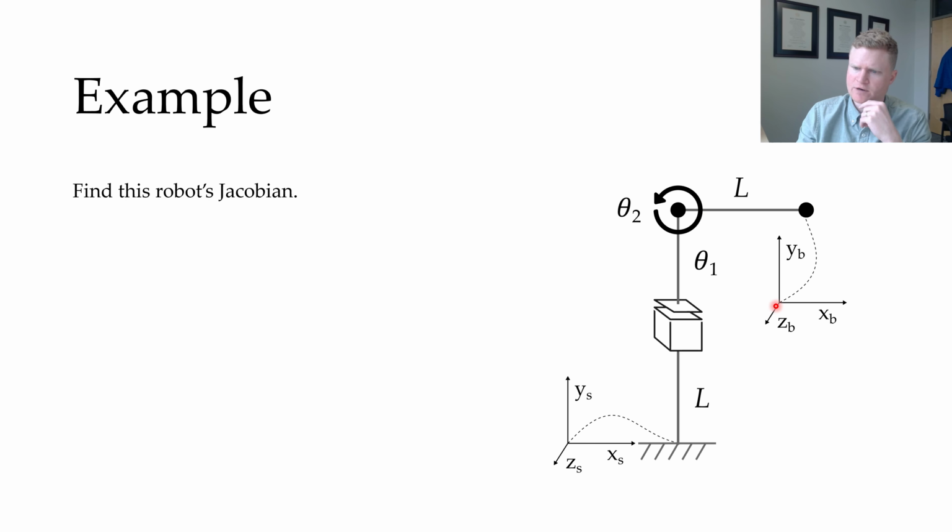All right, so we've got the rules. Now let's go through the process. This should seem pretty familiar. It's the same process we went through with forward kinematics. So finding our first screw, it's 0, 0, 0 on the top because there's no angular velocity for this prismatic joint. And the bottom is just 0, 1, 0, because it's translating upwards, lined up with the positive y-axis.